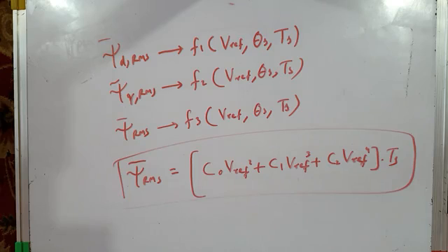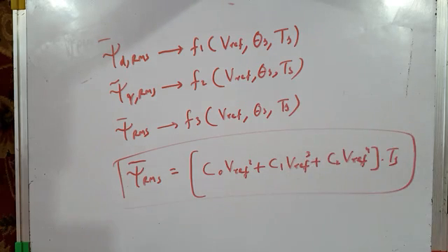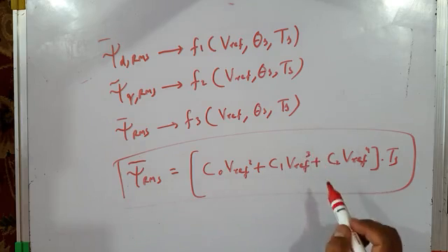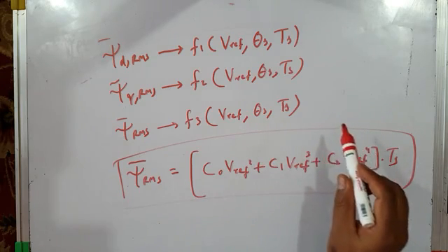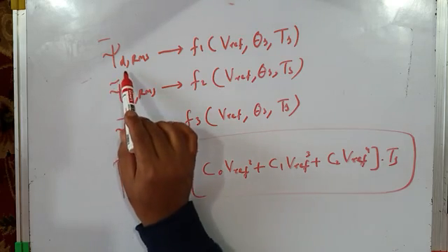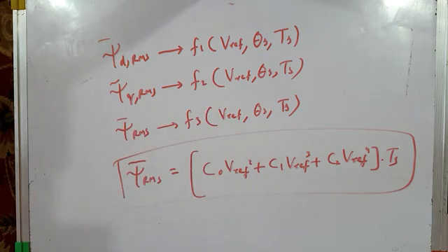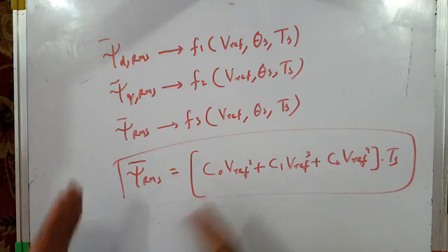So in today's lecture we have seen how we can find stator flux ripple in a dq plane, and how we can then find the d-axis component of stator flux ripple and the q-axis component of stator flux ripple. Having done that, we have seen how we find the d-axis stator flux ripple RMS value and q-axis stator flux ripple RMS value using those equations.